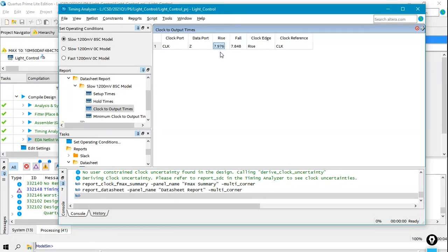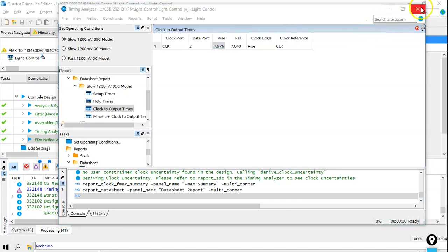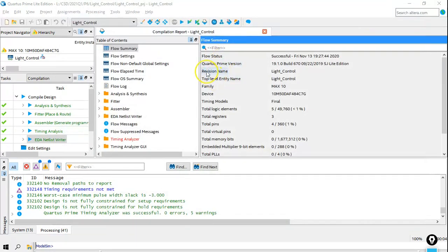So you may very well imagine that this is 7.97, so 8 nanoseconds. So this is exactly 125 megahertz. That is the maximum frequency possible for this circuit. Because if you go faster, the output Z does not change accordingly, right? The system is still in transition and stabilizing to the final value. So now let's switch off this timing analyzer and see if we can see that in the wave,